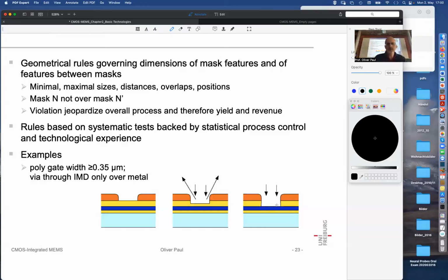Okay, if you do an etching without there being any metal here, so let's assume this blue metal is not here, how does the technologist know when the intermetal dielectric etching is finished? The plasma etcher has some gases that etch, and the chemical composition of the plasma reflects the species that are there.